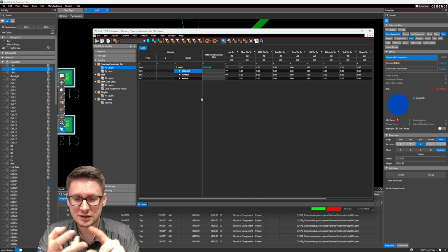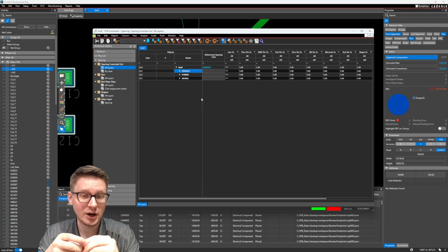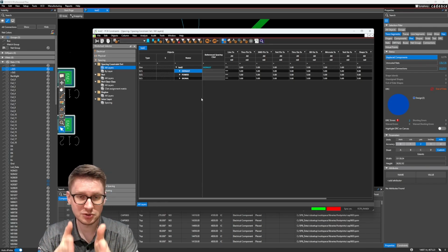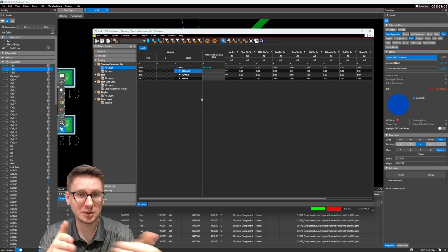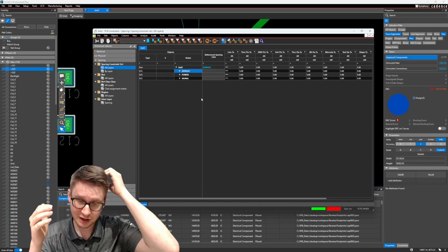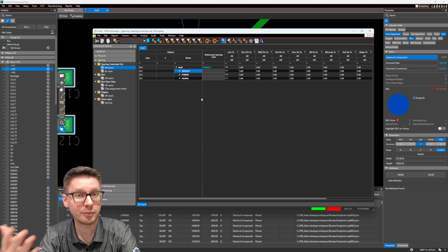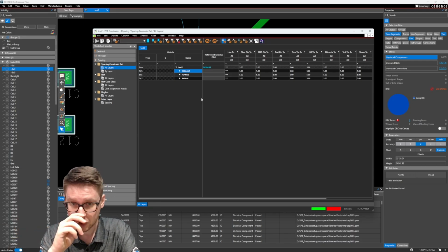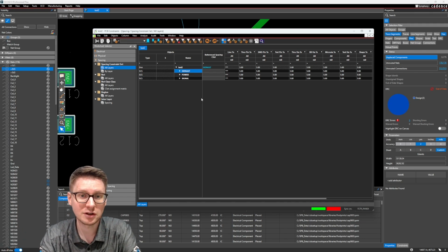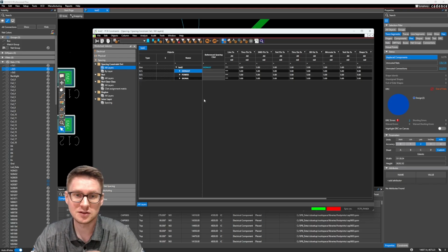The second thing is if you have high-speed signals on your design, you want to make sure that high-speed traces are not routed too close to each other, and that there's no coupling between those two traces enough to have crosstalk, for example. I guess the third is also your manufacturing minimum spacing allowed, which could determine, for example, the price of the manufacturing of your board, or even whether or not it is manufacturable at all, depending on how advanced of technologies your fabricator can support.